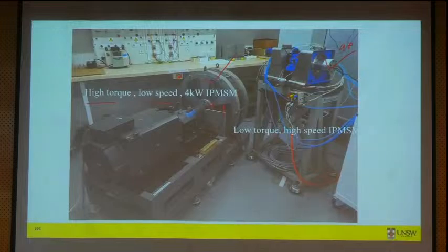And the finding from this design was how to make an IPM motor robust. Even for traction applications, as we have seen, maximum speed is moving to the higher and higher side, 20,000 RPM. And so whether this design concept can be used even for lower speed, not 100,000, but lower. Size will increase as the power level and the speed reduce, but the same robustness can be achieved.